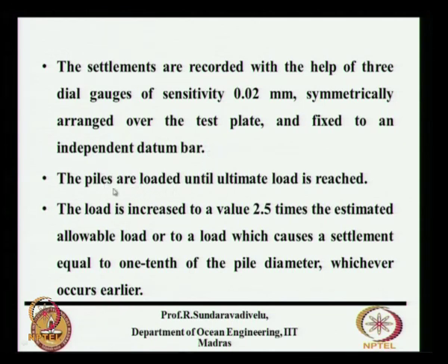The initial test piles you load until the ultimate load is reached. Sometimes you may not be able to reach the ultimate load. In such a case we apply the load up to 2.5 times the estimated allowable load. Suppose 400 tons is the capacity of the pile you need, then you load it up to 1000 tons, 400 into 2.5,